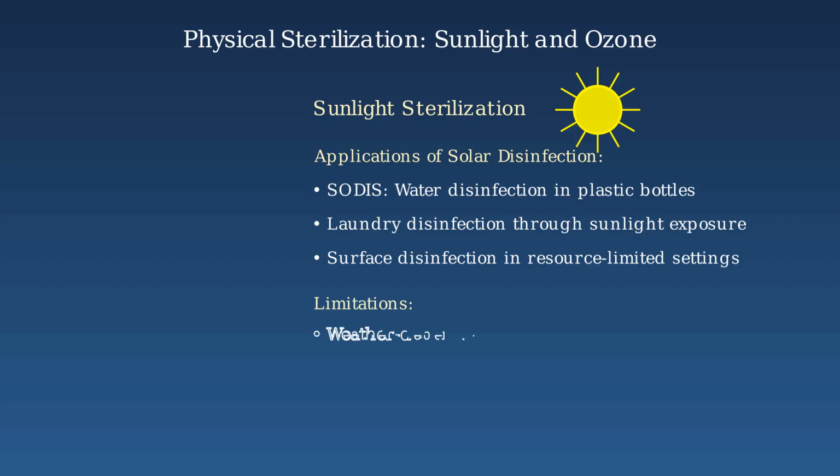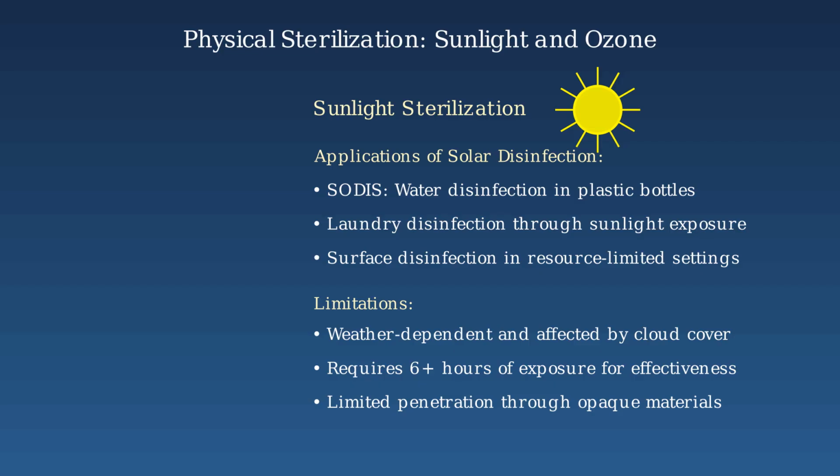Despite its benefits, solar disinfection has limitations. It's highly dependent on weather conditions and cloud cover. Effective sterilization requires at least 6 hours of exposure, and sunlight cannot penetrate opaque materials.